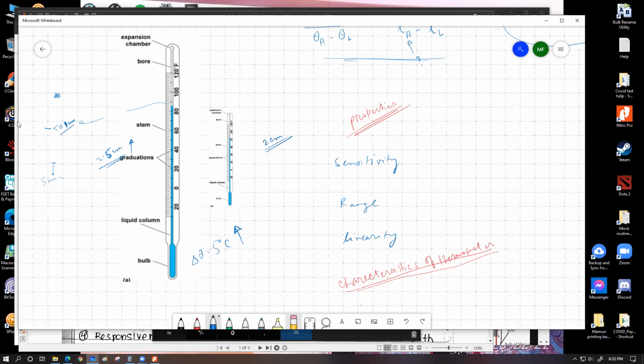Okay, let's say one of these lines has a thickness of 0.1 millimeter. So if we have a space of 5 millimeter, the maximum number of lines we could possibly draw while touching each other, without any gap in between, can be 50 lines. If we want to draw 20 lines instead, how much should be the available gap? 5 divided by 20 gives you 1 by 4, which is 0.25. So from one line to the next line, you're going to have 0.25 millimeter of gap.